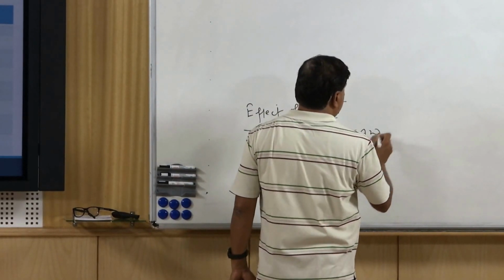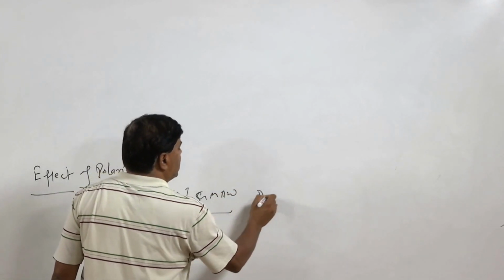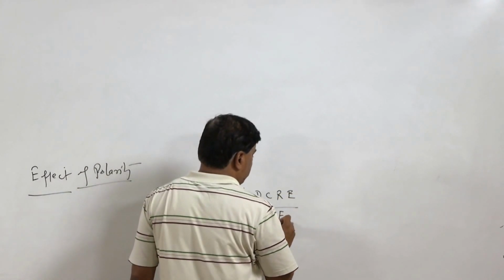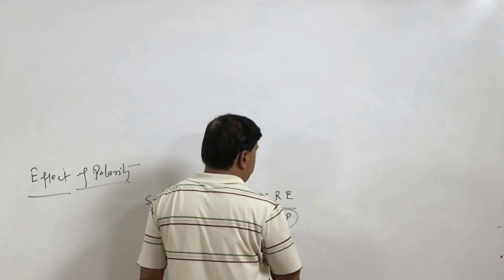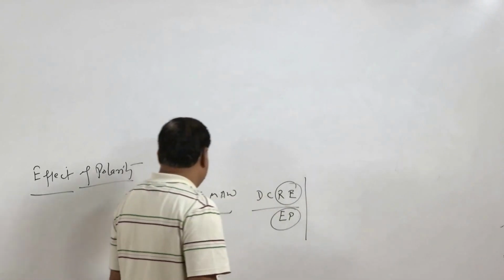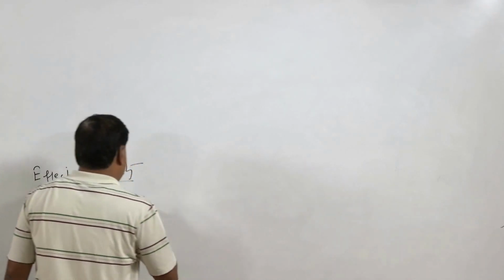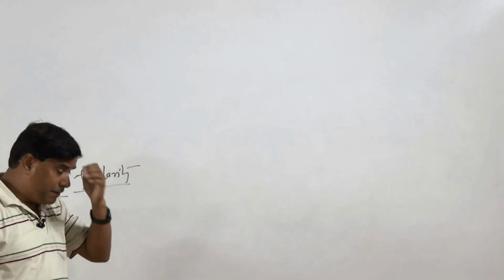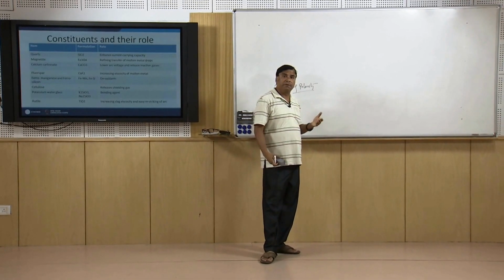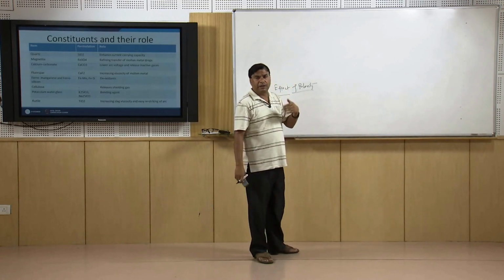So, invariably in SAW, and for the GMAW gas metal arc welding process, DCRP or DCEP, electrode positive or reverse polarity, both are the same, and this kind of polarity is used to have the advantage of a higher melting rate. This kind of facility is available only with DC, where we can select the type of polarity as per the requirement of heat, either in the electrode side or in the workpiece side, whether we want more heat or less heat in the workpiece side.